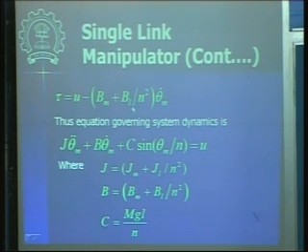Now the second part, you see that there is an n square term here. Bl into theta dot L is a torque. Okay. So where is this second term coming from? It is basically when you transfer that torque to the motor side, you have to again divide by another n. Okay. Because of that you get this n square term. You all understand that? Okay. So in general, your equation then can be written as this.